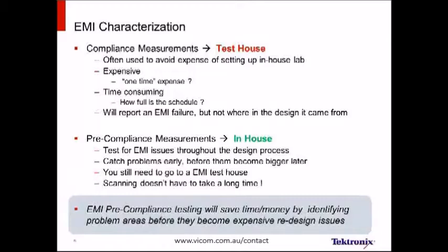When it comes to EMI characterization, we basically have two perspectives. We have compliance and pre-compliance. Compliance measurements involve a large capital outlay, not just for the equipment, but also for the physical setup. To build an anechoic chamber of 3 meters or 10 meters is very, very expensive.